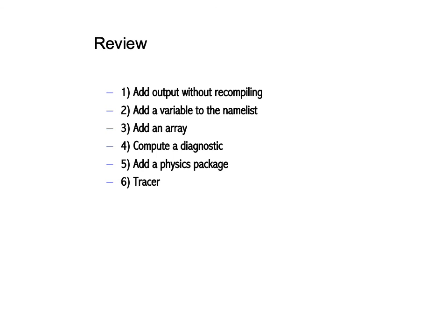The last example was for utilizing 4D arrays inside of the WRF model. Tracers are passive tracers inside of the model, so there are no feedbacks to the model solution, though it does take more memory and it takes more time to advect the additional scalars around. The last important reminder about example 6 is that even though we were talking specifically about tracers, the rules apply for all of the 4D arrays.